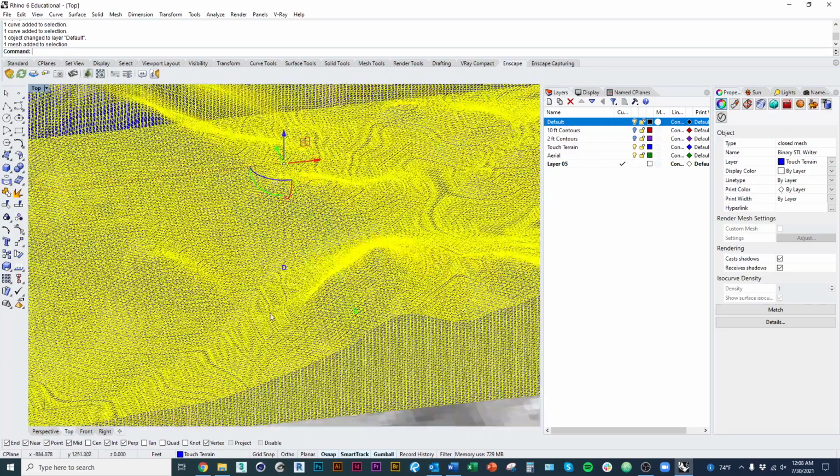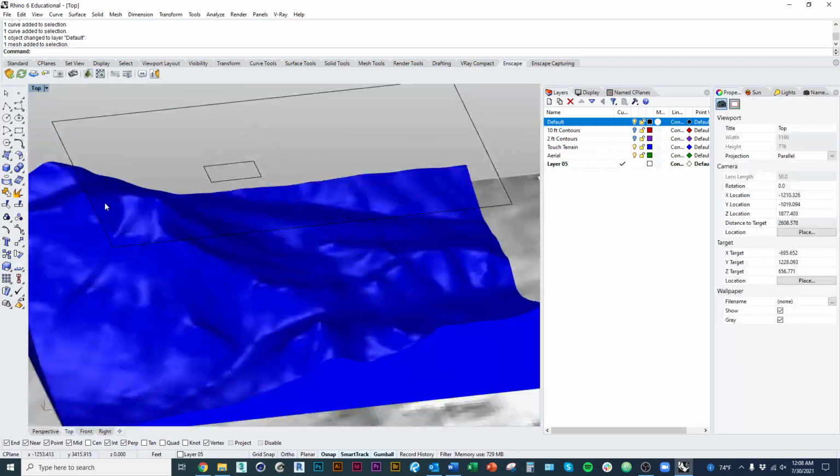I'm going to use it to make a NURBS surface, which is easier to edit in Rhino. And then I'm going to crop it down to a smaller dimension and scale it, and then turn it into a step file or a contour file for a template for a physical model.